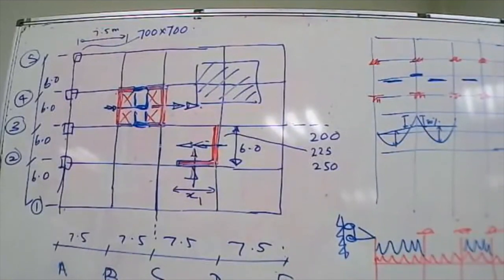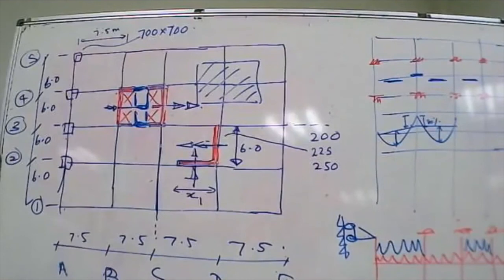For the core wall, if we are confident that the bracing in all directions is firm, can we consider it as a box section, a hollow section, when we calculate the second moment of inertia? Yes, you can. And in programs like ETABS, you can actually make it happen. But when you're doing manual calculations, it's not worth trying to do so much extra calculation.